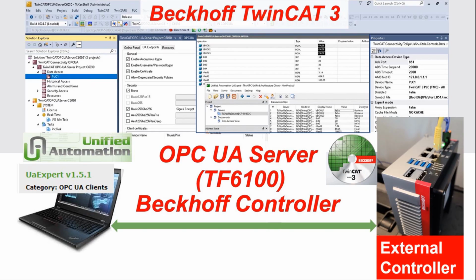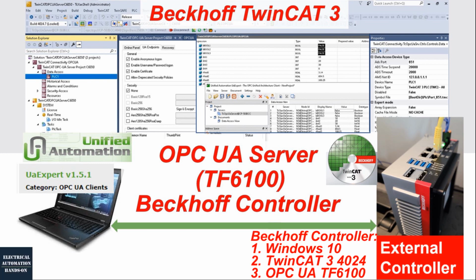Hello everyone, in this video I would like to show how we can configure OPC UA in one Beckhoff external controller. That means I will use my laptop as an engineering laptop and configure one external controller, a Beckhoff IPC, an industrial PC. This Beckhoff IPC will run the TwinCAT runtime and the OPC UA server.